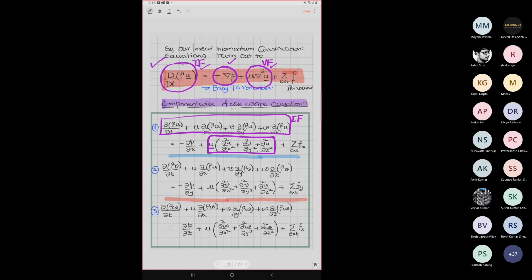Maybe you have an incense stick you are lighting, and there are always plumes wandering around. Compared to the viscous forces, which try to make it a smooth laminar kind of motion, your inertia forces are somehow triggered so large that it becomes turbulent. So whenever your inertia forces start dominating, the particle acquires huge amounts of accelerations and velocities, and moves in a very complicated way.